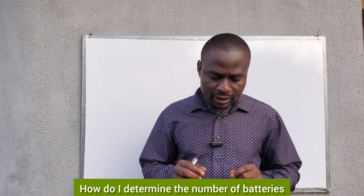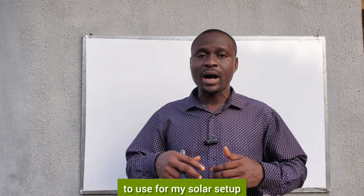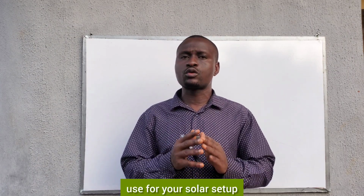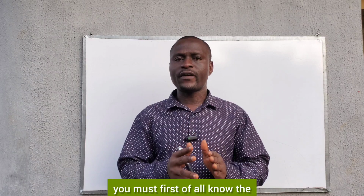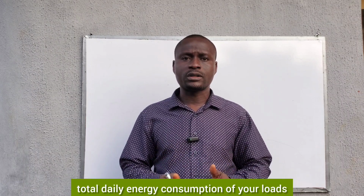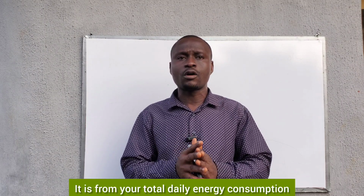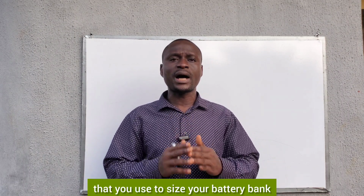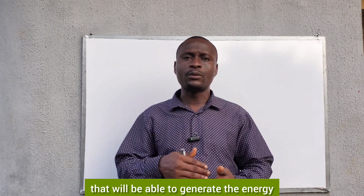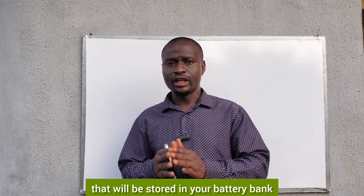All right, question number 1. How do I determine the number of batteries to use for my solar setup? So, for you to know the number of batteries to use for your solar setup, you must first know the total daily energy consumption of your loads. It is from your total daily energy consumption that you size your battery bank and also size the number of panels that will be able to generate the energy that will be stored in your battery bank.